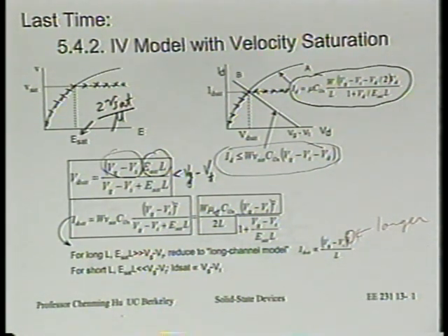And there's an interesting lesson here. That is, even with a 0.2 micron channel length, the transistor IV curve behaves just like our classical model in the range of Vg not being very much larger than Vt. Did you follow that statement?